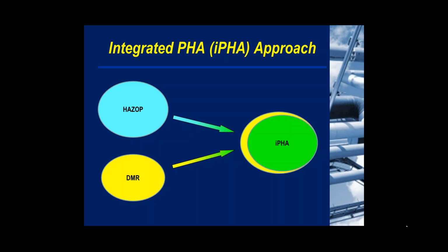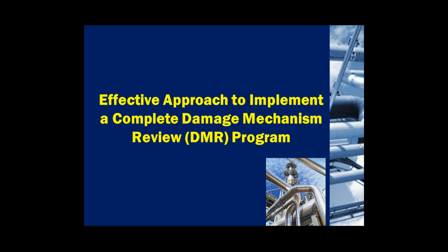And then at the very end of the HAZOP study, as part of a streamlined approach, you can apply a more extensive checklist, take a look at the programmatic elements, your mechanical integrity program, how well it's being implemented, and as necessary, it's an opportunity to precipitate recommendations for further review of the program, or if you're not able to keep up with testing and inspection activities, are things properly prioritized?